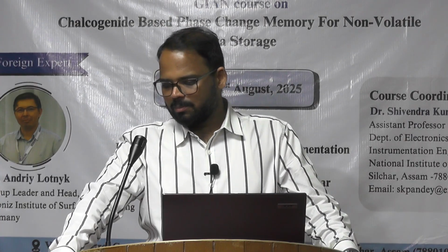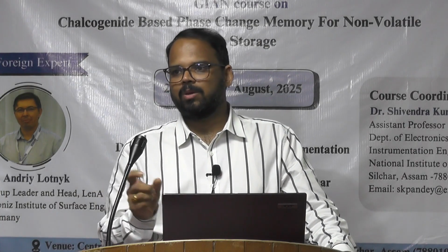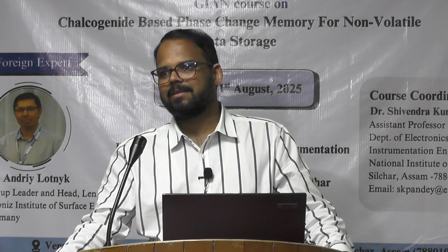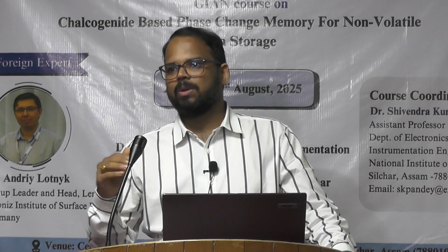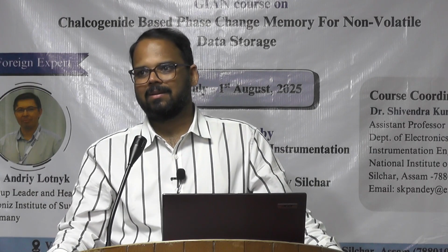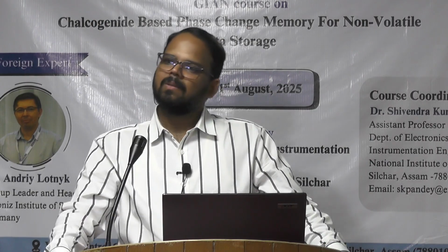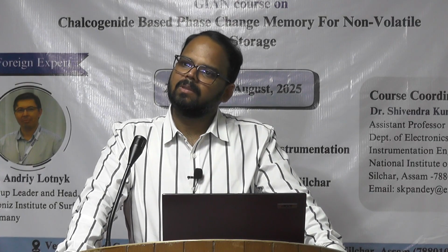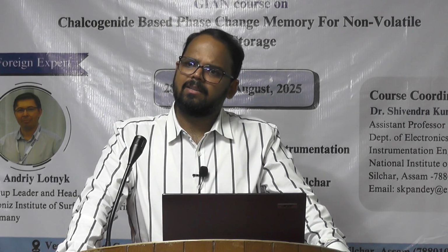But in case of voltage, possibly, in what I'm thinking, I think you are just providing a sweep, means just 0 to 5 volt. And what is the step size you are taking? Step size is 0.1 volt or 0.5 volt, because sweeping means you should have an appropriate step size. So we are having nearly 101, like 100 steps. So in current mode, I usually set the current from 0 to 5. Okay. And with 100 data points in between. Yeah, with 100 data points in between.